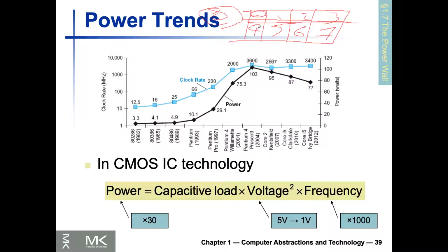First of all, the heat they generate affects the performance of the adjacent cores. And if they are at 100% load, the power consumption would be very high, causing battery issues, power issues, and so on. You can see the governors even in your cell phone if you install an application to monitor your CPU, for instance CPU-Z.